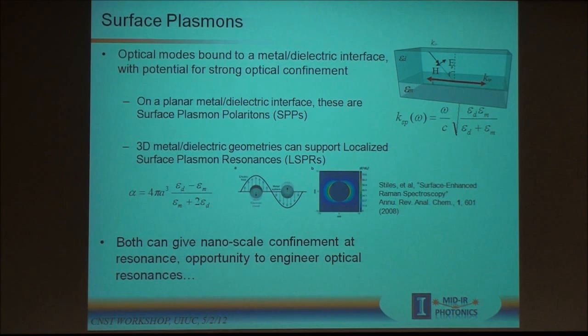Now, plasmonics is a hot field, and a lot of people are worried that it may be one of these buzzword fields because one of the issues with plasmonic structures is, of course, loss. But if you actually think about what we're interested in doing in the frequency range we work in, we actually want loss. Loss is fine, because if you can engineer a loss, that effectively gives a selective thermal emission when you heat up the object. So in fact, what we're trying to do is engineer losses onto our surfaces and use those, for instance, for thermal emission.